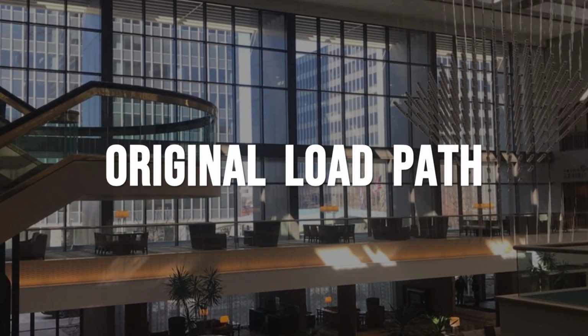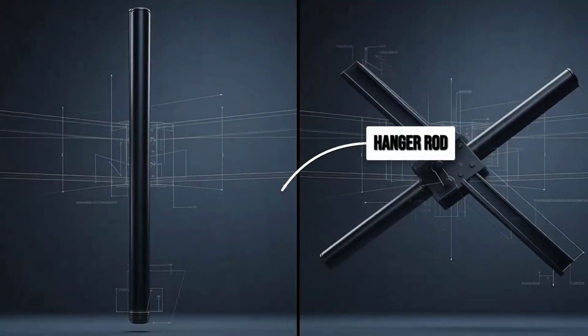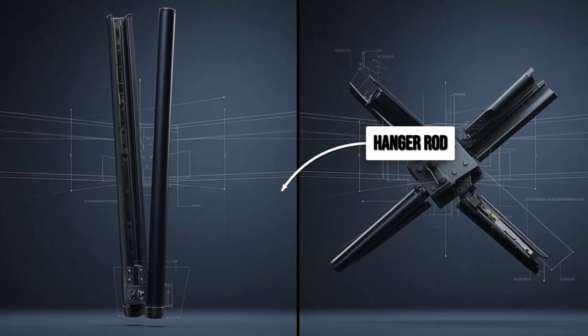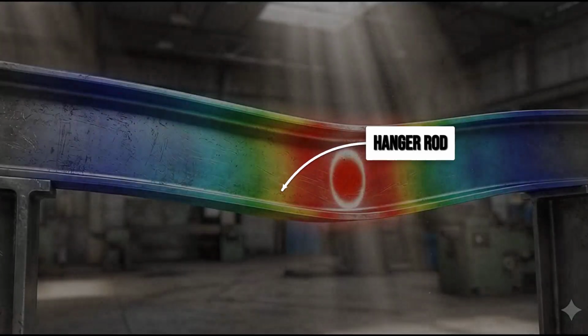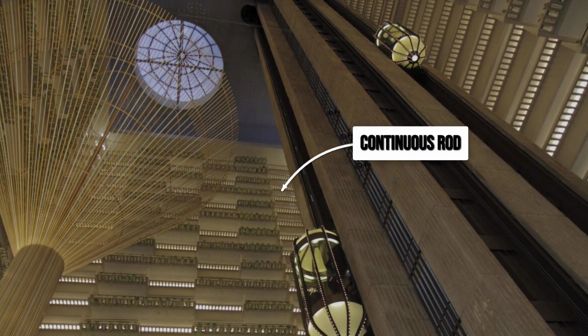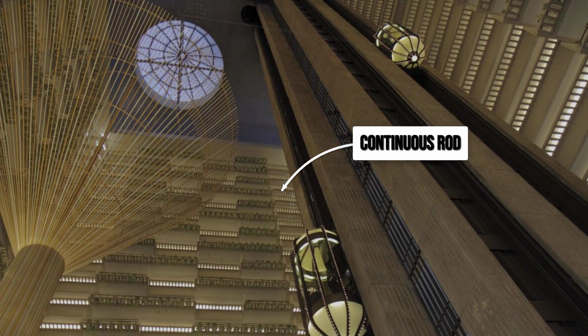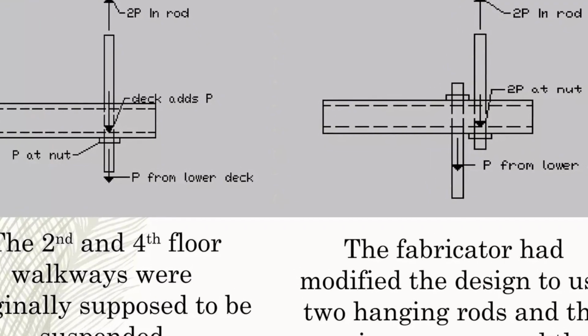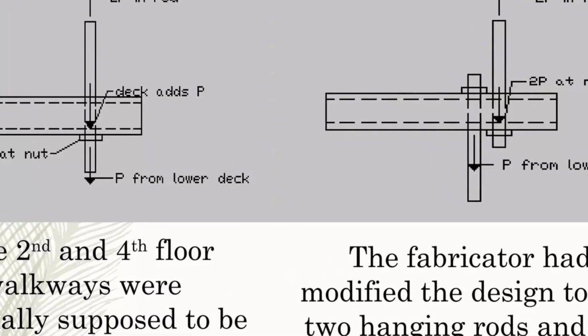Steel rods, stretching from the ceiling to the floor, defined the heart of the Hyatt Regency's atrium. The original design called for each hanger rod to run in one continuous line, threading through the fourth-floor walkway, then passing straight down through the second-floor walkway, before anchoring at the ceiling above. At each level, the rods simply continued on, never stopping, never splitting.